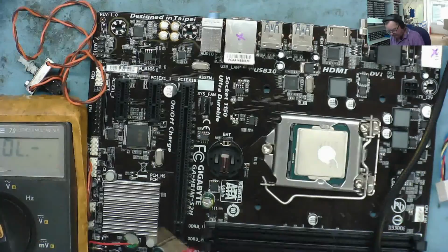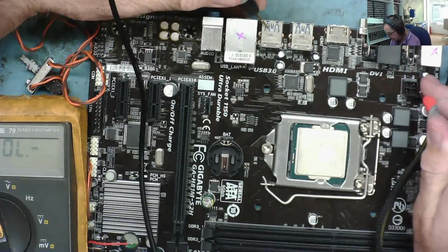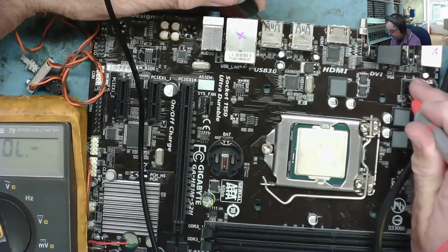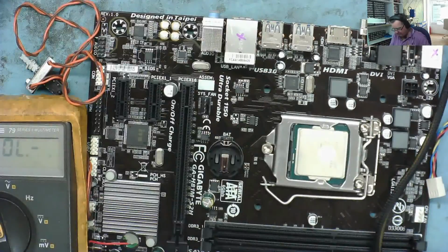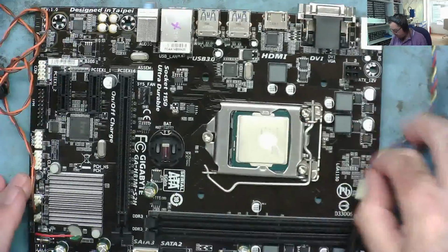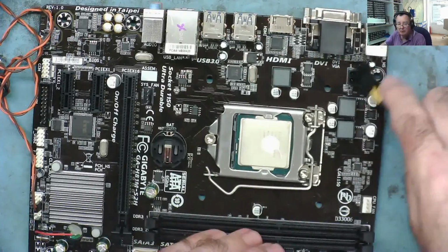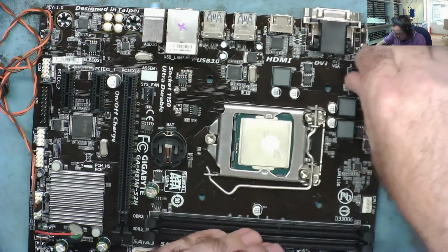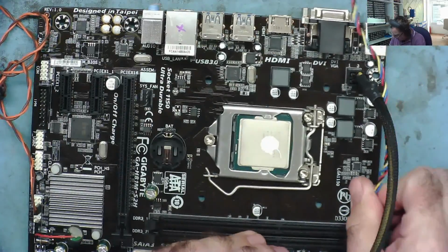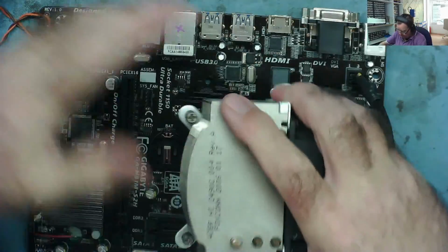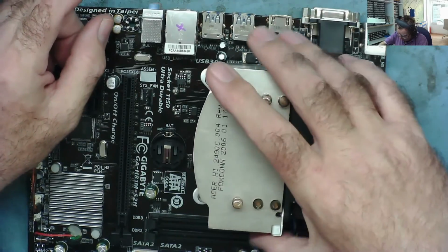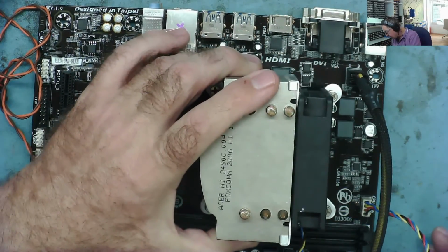This didn't have any shorts on the 12 volt last time I tested, but as soon as it's been in the sink we'll just test it again. That's okay, these two are the ground ends, so that's okay. So there's still no shorts, which I wouldn't have expected. It was okay before. We'll put the 12 volts on that then, and there we go. We'll use our fan that we use for diagnosing, the one that we just balance on to the board. These legs are too short to actually reach the board, so it's quite useful for this. It sits on there quite nicely.